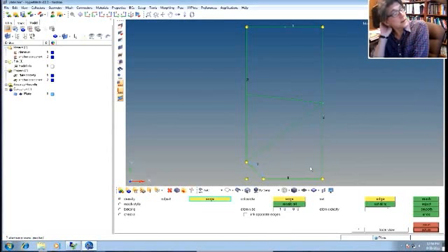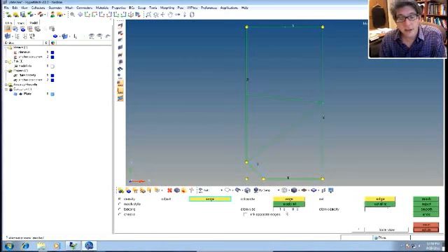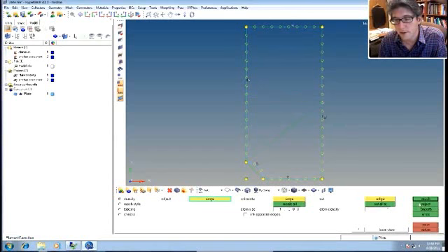This is something that you want to really get to learn how to do in HyperMesh, because the quality of your mesh is really important. There's a couple of things that you can do. One is element density, and then there's element size. You can set globally the size of an element. So let's set it at like 1. And then if I do recalculate all, you can see it starts to give me a hint of the element distribution. So I can do a reject, throw out that old mesh, and do a mesh.